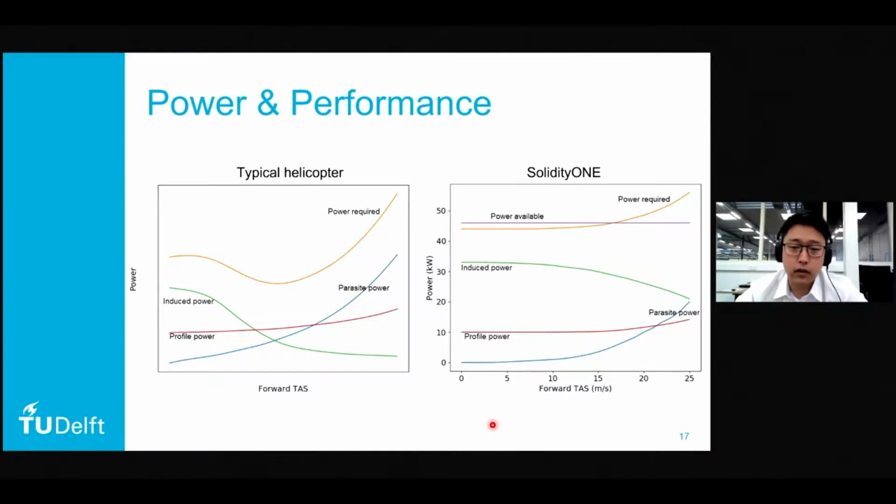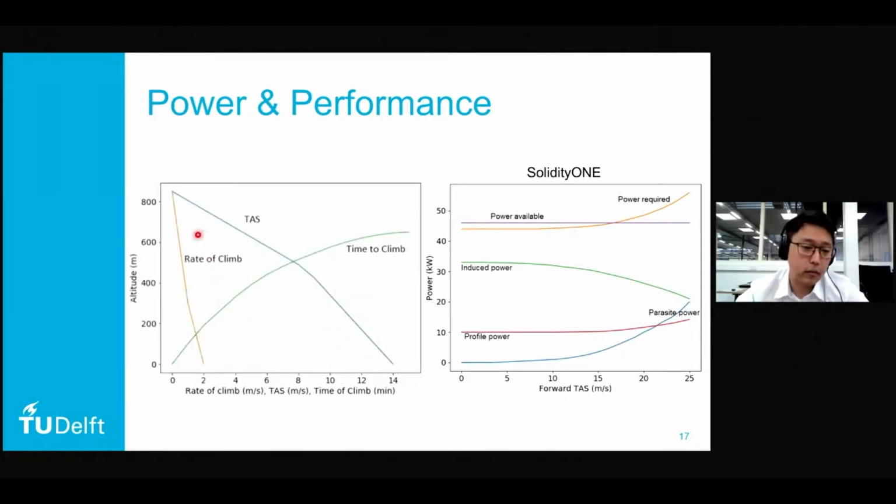This limits our top speed to about 14 meters per second. And as you can see, we theoretically could fly at an altitude of 830 meters. However, due to having a 5 minute battery, you would actually only reach about 420 meters, and you will have to figure your own way back down. Now I will hand the word back to Nick, who will take us back to the competition requirements and see how we compare to comparable aircraft.